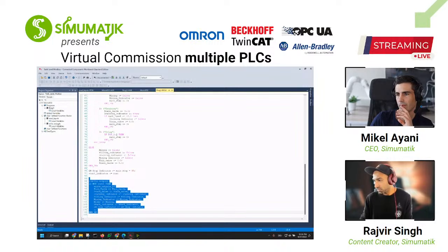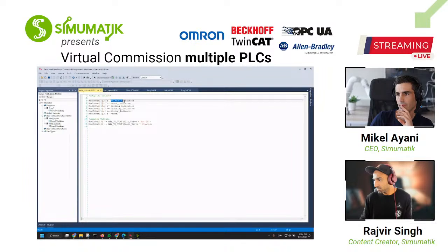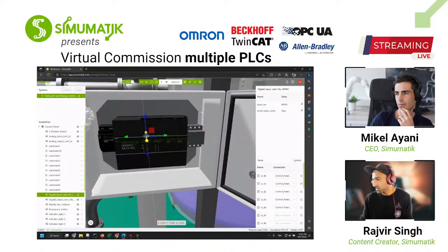To write the outputs, I have another function, which is going to read from the variables which I have in the PLC program, and write again to the Modbus output. So the steps are: first, you read the inputs, solve the logic, write the outputs. That's it. So this is the PLC program.